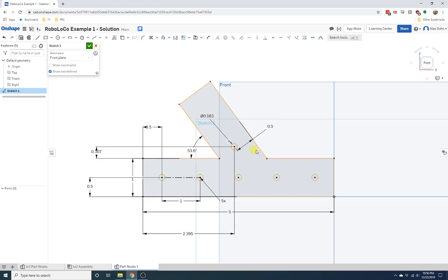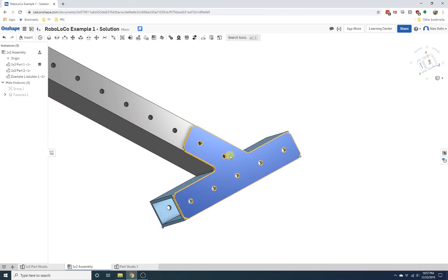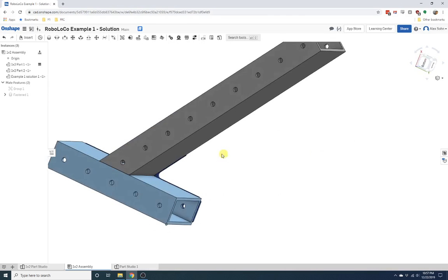That one is a little bit more complicated, but what's cool about the patterns is we might try to do this pattern in a different way. I'll do it in 2 different ways. Okay, so we'll do the rectangular pattern. We're going to click this. But you notice it only goes left and right. That's kind of unfortunate. But this is what we're going to do. We're going to change this. How many holes do we want? So for the other one, we're going to do something slightly different. Let's say we want 3 holes instead of 2. So this one uses 2.